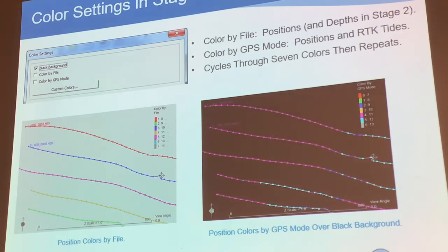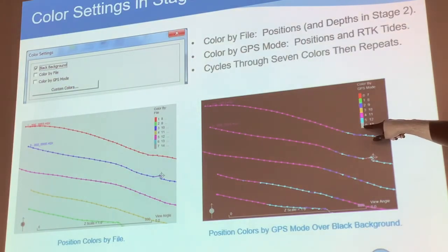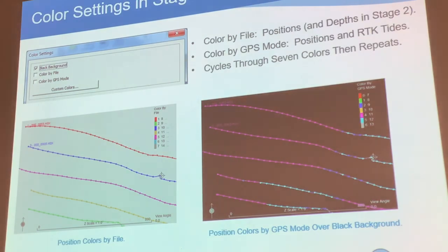No, okay, so your GPS quality, the L band is basically the correction. But GPS quality just shows you whether you are getting your L band or whether it dropped out. Over here, like I show you the example, this is GPS quality 0 to 5. This is 4. 4 means it's very high accuracy.